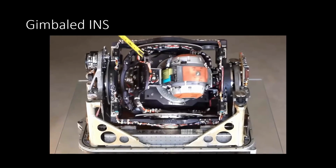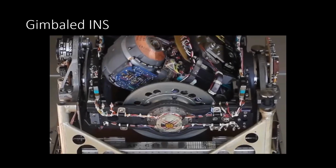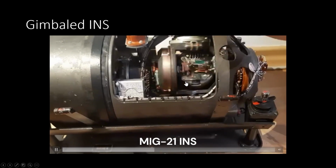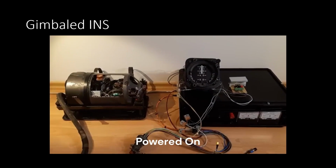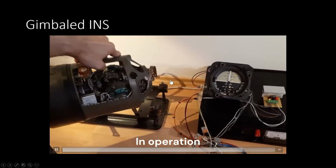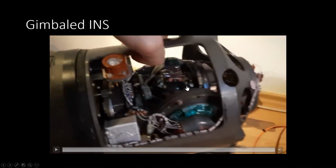So here is a practical inertial navigation system. Let's watch a fascinating video featuring two gimbaled inertial navigation systems, one from an American aircraft and this is from the Russian aircraft, MiG-21. You can see the gimbals in action. You are not able to see the sensor assembly inside it. And notice how once we power up this system, all the gimbals get aligned, and now we are going to move around this, simulating the aircraft movement, and you can see that the device is tracking the aircraft motion. See how the gimbals are aligned. In practical application, these gimbals will be aligned with the north, east and down frame that we talked about.